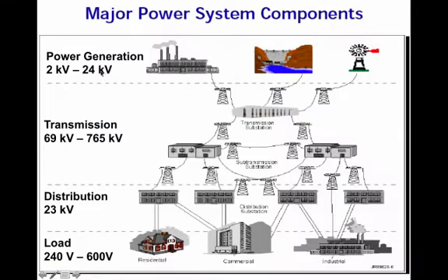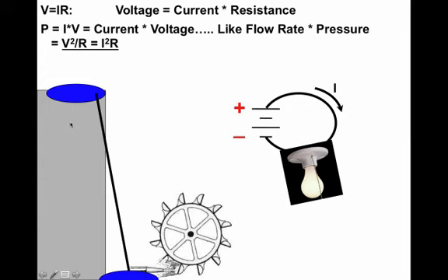The electricity that comes out of a generator facility is about 10,000 volts. In order to transmit it long distances, we then step the voltage up to about 500,000 volts, and we step it back down to bring it to your house, eventually down to the 120 volts AC that you get. Higher voltage means less power loss, and that's why we boost up the voltage. Let's take a look at why that's the case.